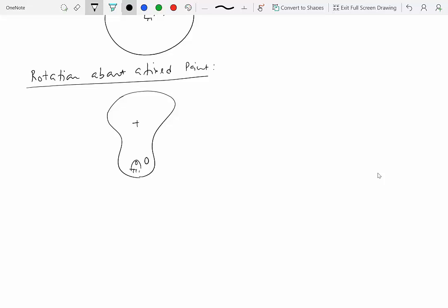So let's say the center of mass is here. Clearly if this is rotating with angular velocity omega, then we can find out what Vg would be. Vg would be equal to the distance from O to G, let's call it rho, times omega. We don't care about the vector quantity over here because we're just dealing with scalar quantities.